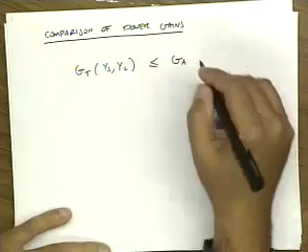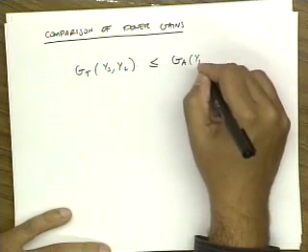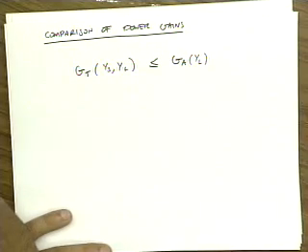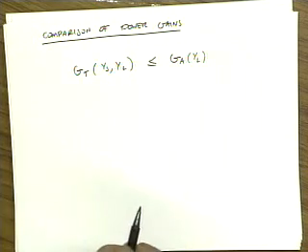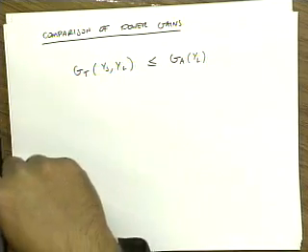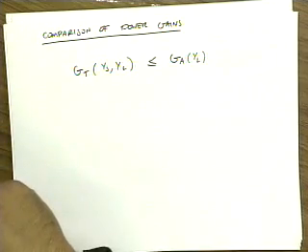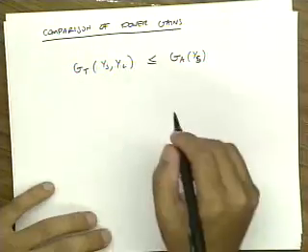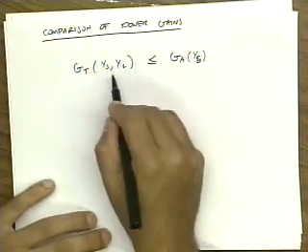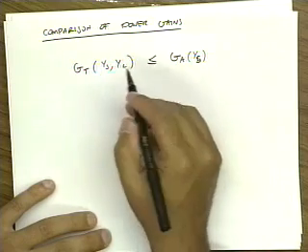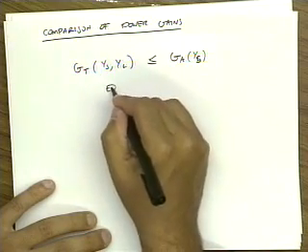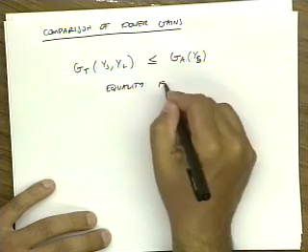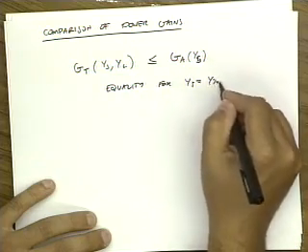The available gain is power available from the two-port divided by power available from the source, so it should only be a function of Ys. And we found that equality only happens for Ys equal to Yin conjugate.